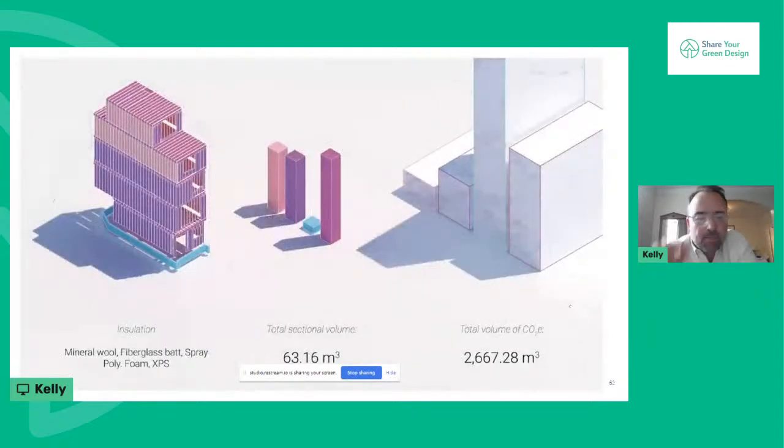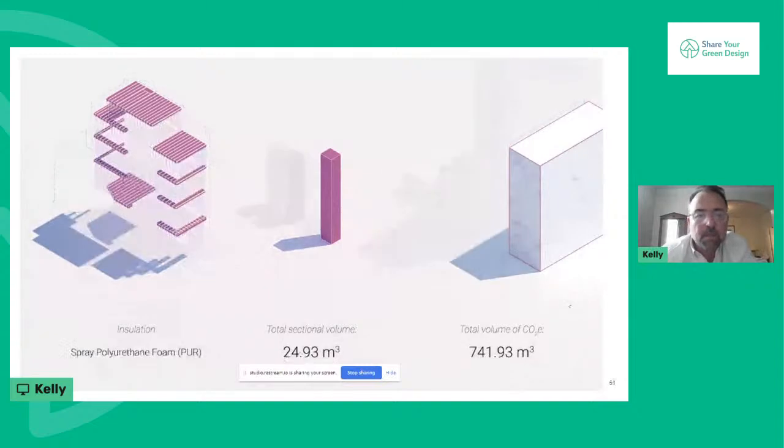But back to the insulation here, you can see XPS, that small little block in the middle for that foundation, enormous, off the charts on the right. And this is a material we've been using, certainly not thinking too much about it, for the last 3 decades, blindly not knowing that it's ripping a hole through our ozone. The stuff we took out of our fridge in the 80s, we decided to repackage and put on our foundation. And specifically spray foam.